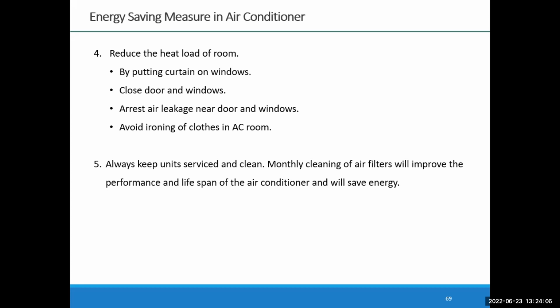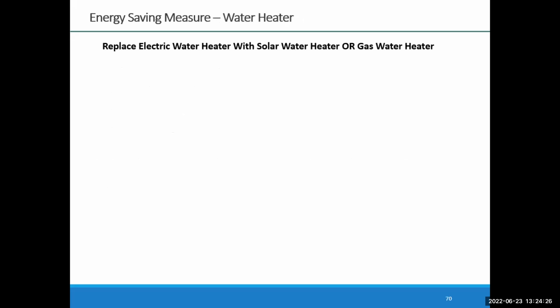Otherwise, the refrigerant in the outdoor unit will not get cooled, and it will actually increase the load on the compressor also. That also will impact the energy increase. Monthly cleaning of air filters will improve performance and lifespan of the air conditioning unit, and also save some amount of energy.